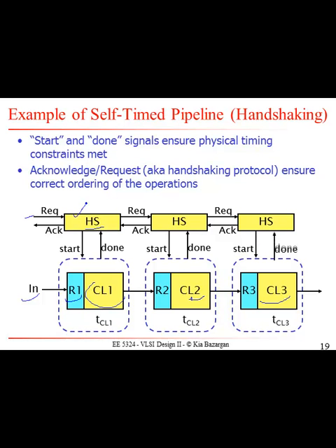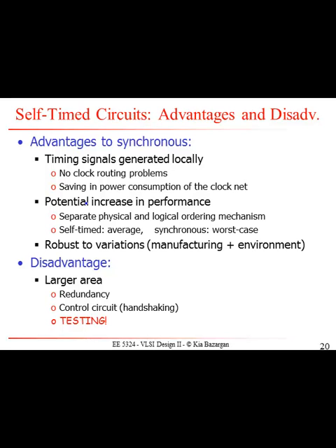So let me walk through this fast. Basically the benefits would be these. Number one, you get rid of that clock signal with the huge capacitive load and a lot of power consumption. So you throw that out, which could bring down the power consumption of the chip significantly.